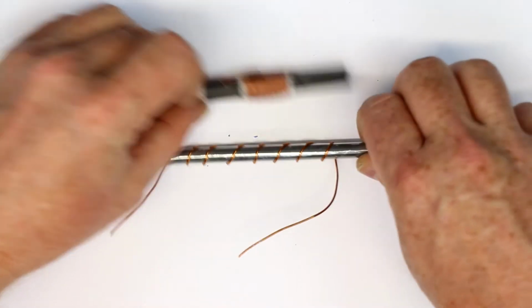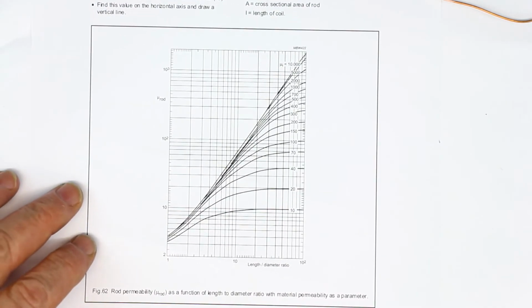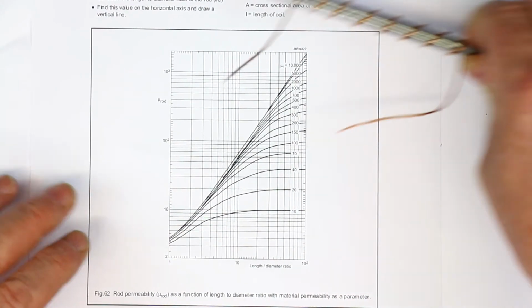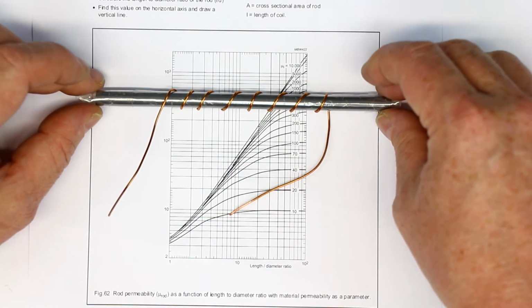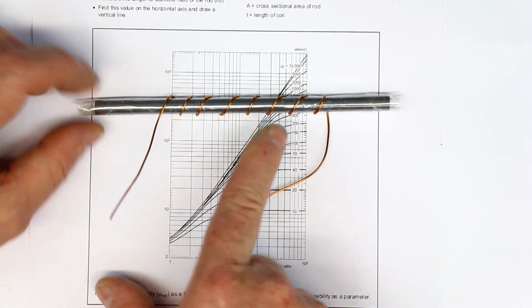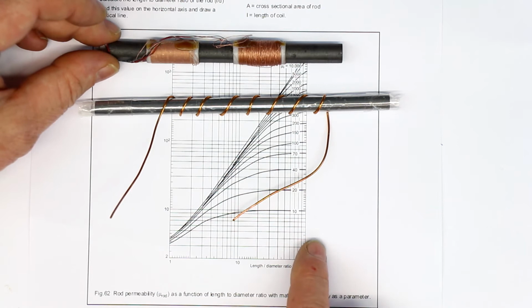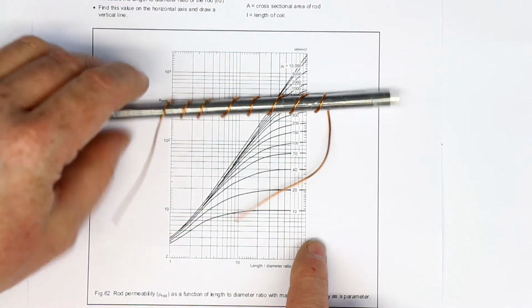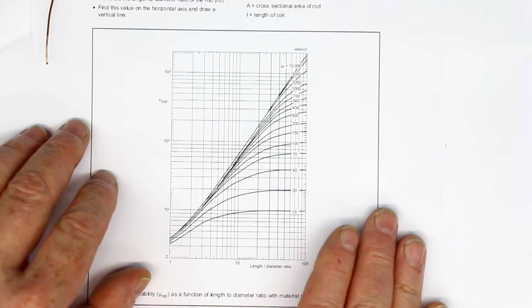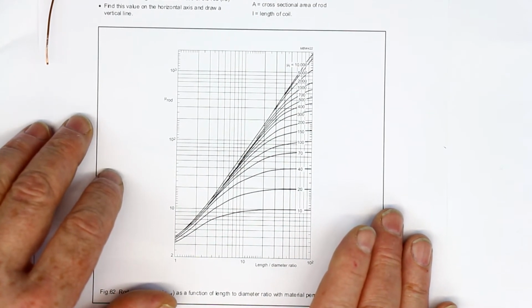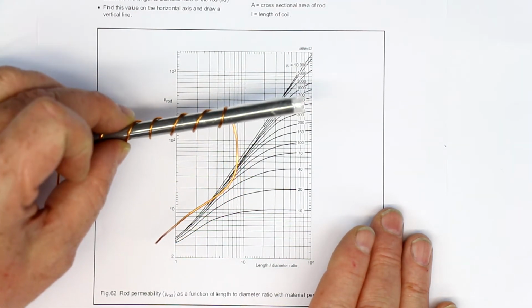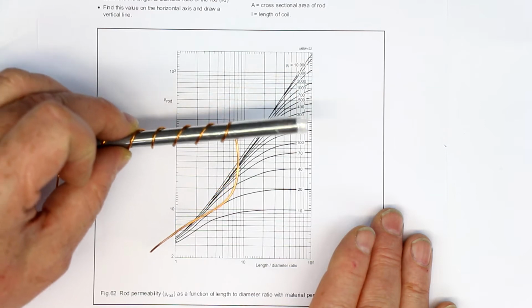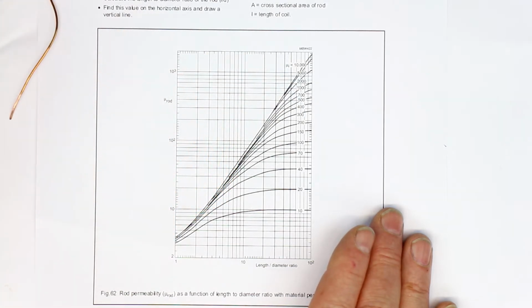I will show you in a second a graph which I already presented in a separate video about this special shortwave Ferrite-Rod, which is made totally different than the ones for the medium and long wave range. Anyway, even if you have a good data sheet for your ferrite material, that would be the first thing you need just to get the so-called μr factor.